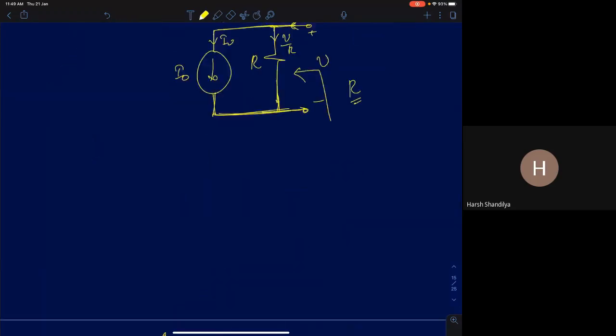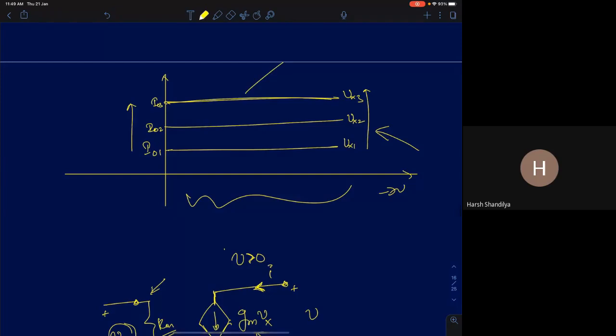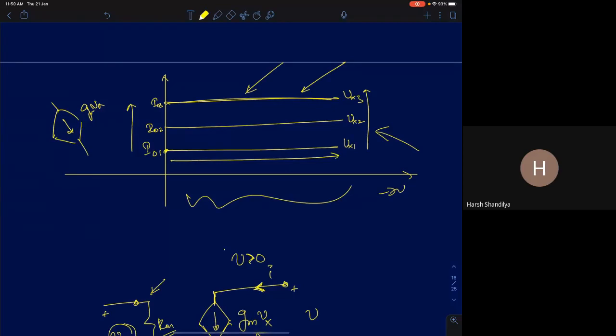So then the same thing, I said, if you have a graph that looks like this, where the current is increasing with voltage, then the mathematical model for this is a transconductance amplifier, a voltage controlled current source. It's a current source because it's independent of the voltage across it, right? Even if the voltage is changing, the current is fixed, but it is dependent on some other voltage, Vx. So that's why I modeled it as GmVx as a current source.